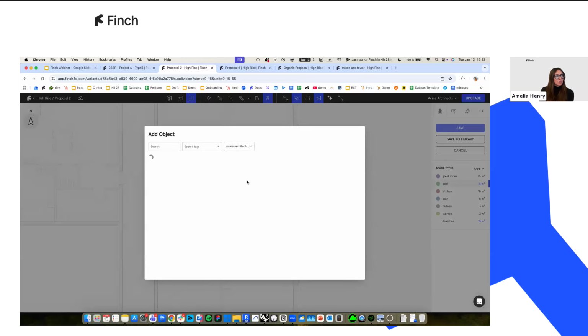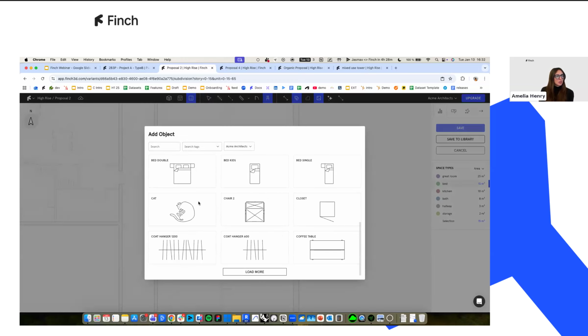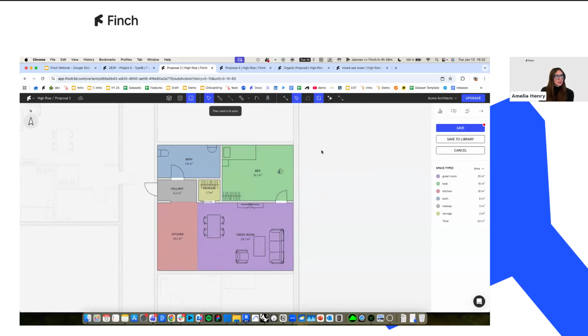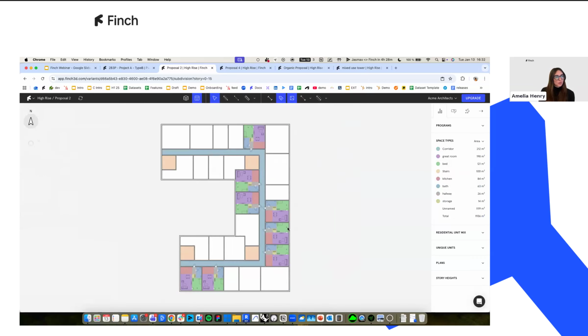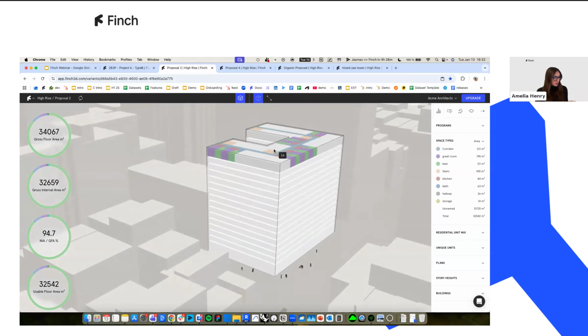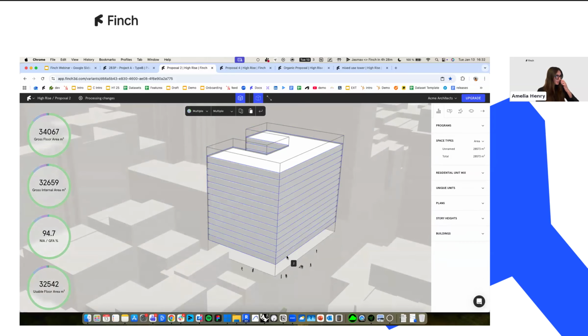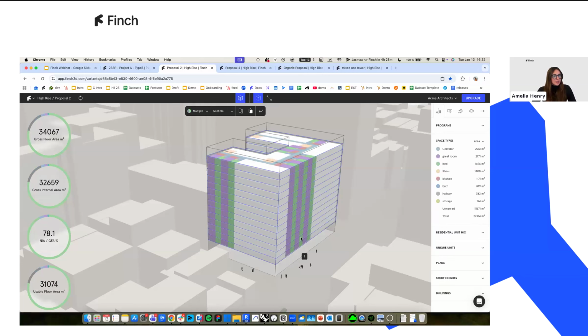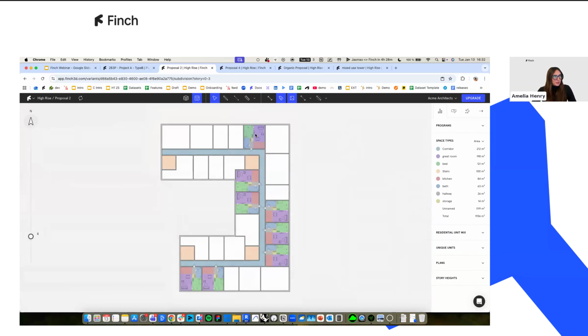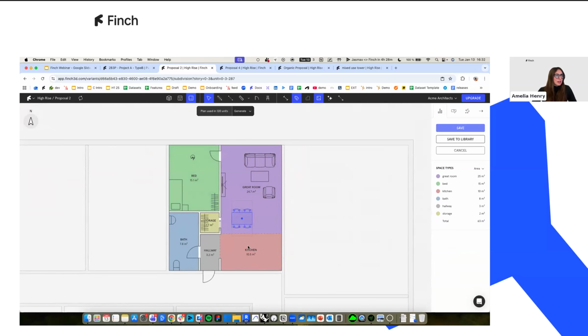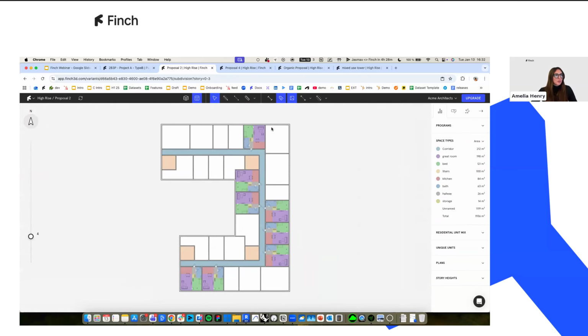So if I go ahead and look at my firm's furniture library, we can drop a cat into the bedroom, and that's committing to all 8 units. And of course, any edits to those will commit to all. If we next just go ahead and Control C, Control V. Now we are going to drop this right through the building and create a really nice model group with, let's see how many units on it, 120 units, all editing simultaneously, super snappy. And of course, that will be brought into Revit as that model group. So it goes really fast to kind of populate through a project.